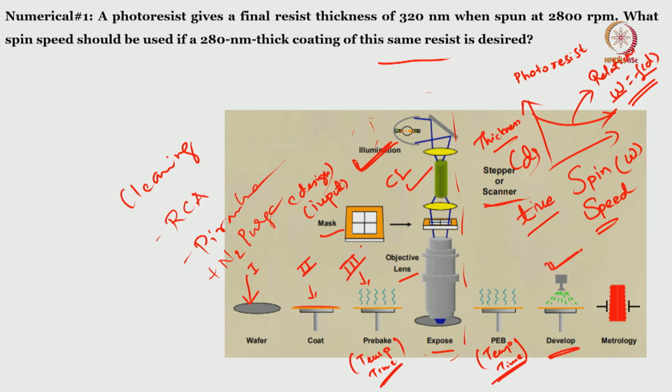So, basically in simple words, what exposure does is it maps your mask design in terms of different chemical regions on your wafer, which you can further use when you develop it. Your final desired pattern will either stay there or get etched, and the other part will get removed, based on which kind of photoresist you are using.